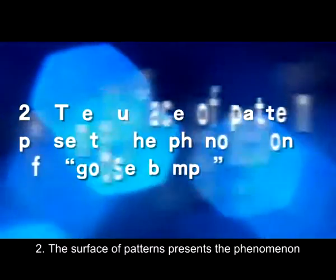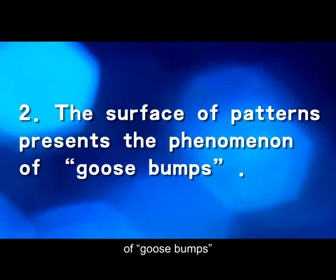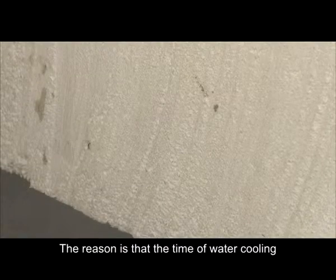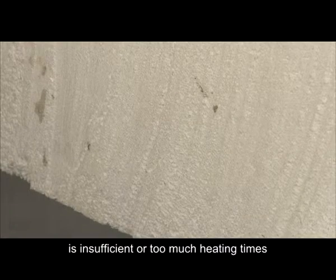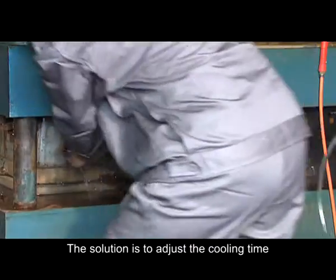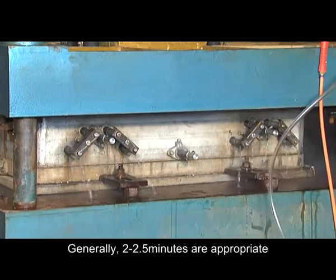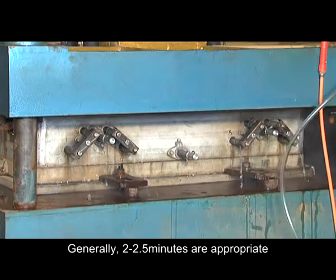2. The surface of patterns presents the phenomenon of goose bumps. The reason is that the time of water cooling is insufficient or there are too many heating times. The solution is to adjust the cooling time. Generally, 2 to 2.5 minutes are appropriate.